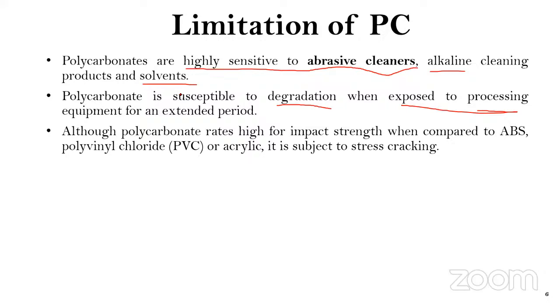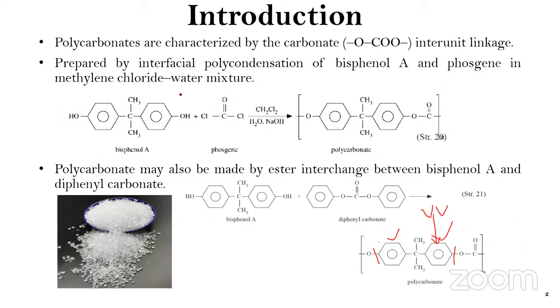That is the reason why, even if a material is very thermally stable. I'll tell you the reason. When this kind of structure is present, it has some limitation, meaning it has this double bond. When you apply maximum temperature, this bond gets a lot of energy and will break into two, forming two free radicals.